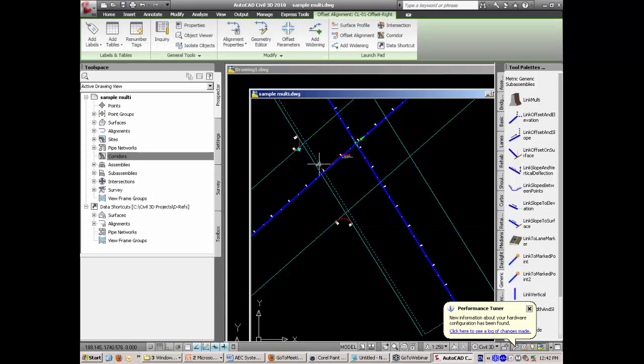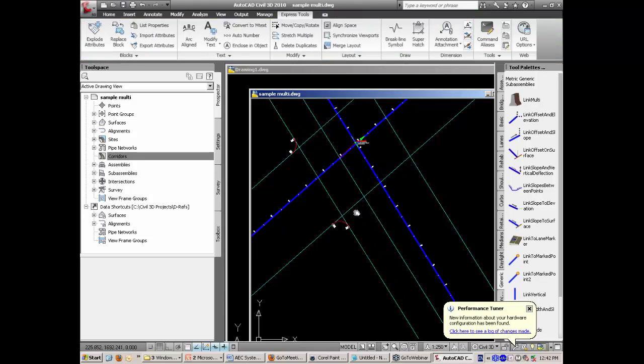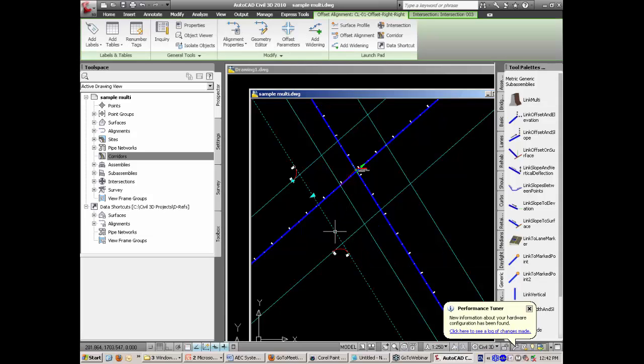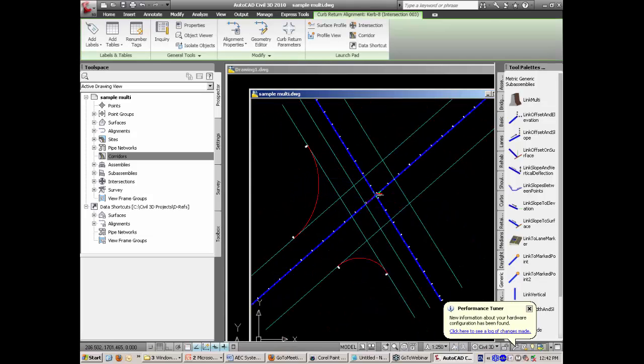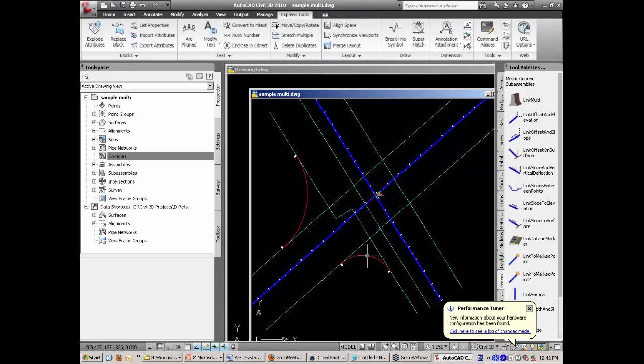So I can press this here, I can pick my curb returns, make them far wider. So this, let's just press the second offset here. So this setup, we've got our outer extents, which is the line I just highlighted. We've got our center line of our carriageway and our main center line. And if I press these and drag these out, I can now go to this outer extents one here, add a separate widening component, so I can make my acceleration and deceleration lanes.